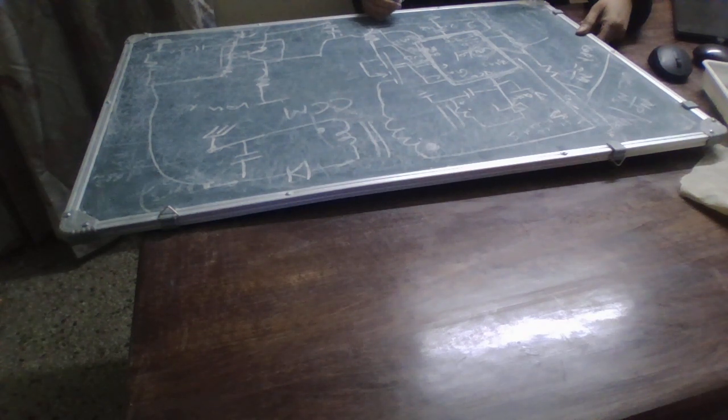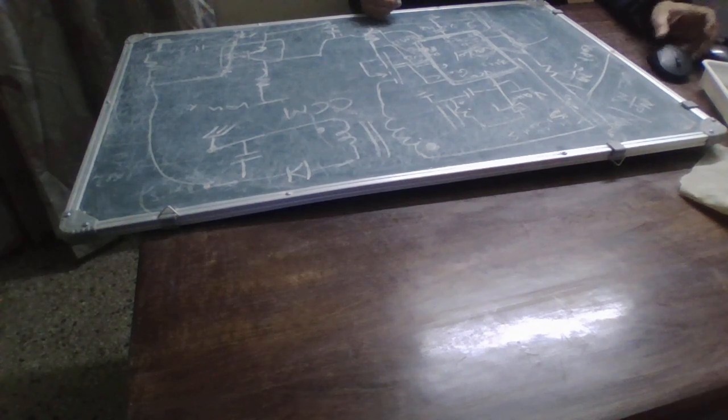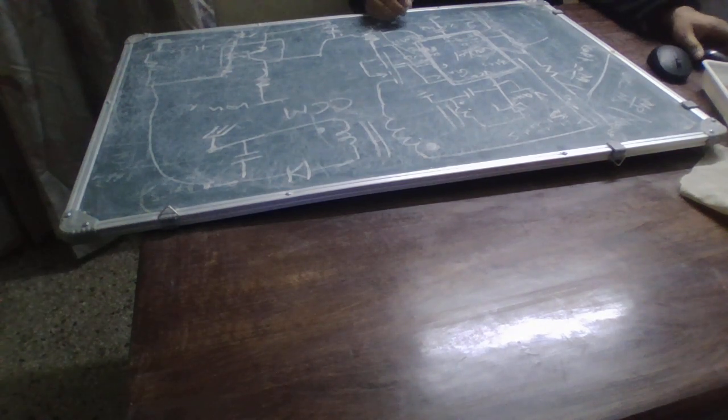As I have said here, I am going to use a duty cycle of less than 50% because I want to have a buck operation from this flyback transformer.